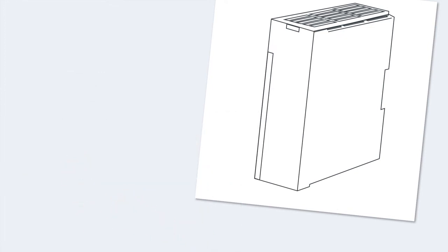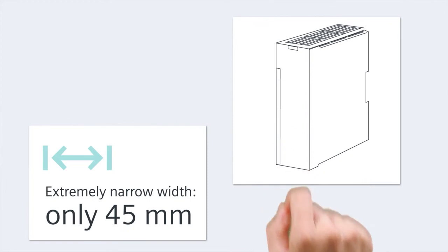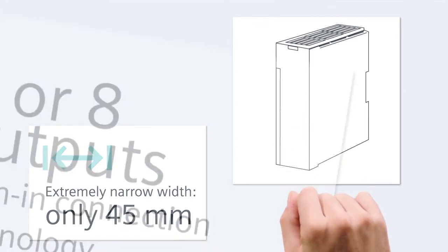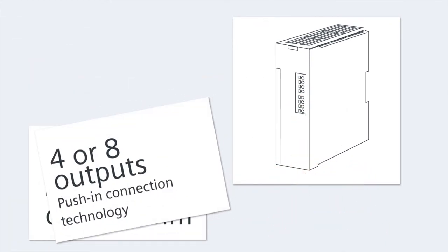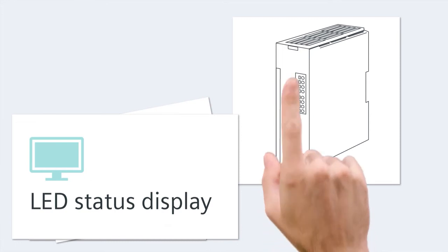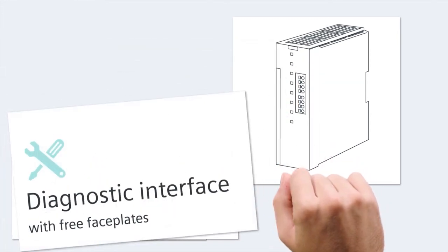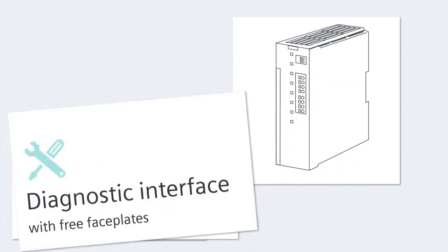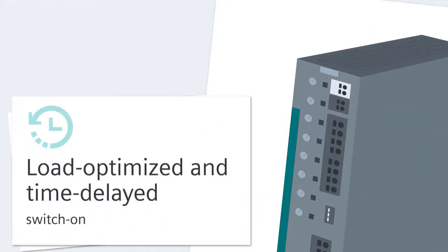They have an extremely narrow width of only 45 millimeters, 4 or 8 outputs that can be set between 2 and 10 ampere, and push-in connection technology, as well as an LED status display and a diagnostic interface with free faceplates. They also permit load-optimized and time-delayed switch-on.